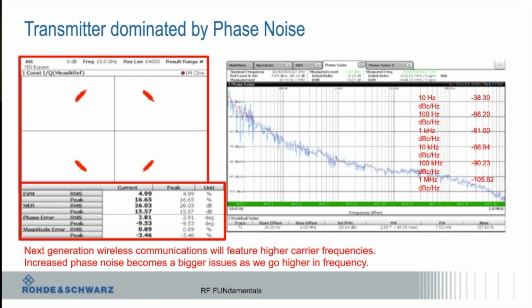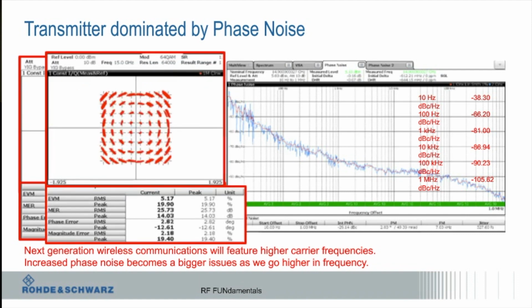That's from phase noise, right? Because the phase noise of the LO internally of my receiver is adding that rotational error to it. Okay, and if you look at a larger constellation, this is 16 QAM. You can see here, the more points I get, obviously the more critical it gets to deal with these noise errors. And I don't think I have a plot in here. Maybe I'll find it later.